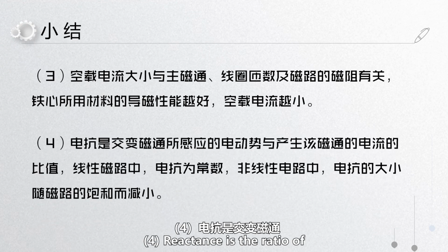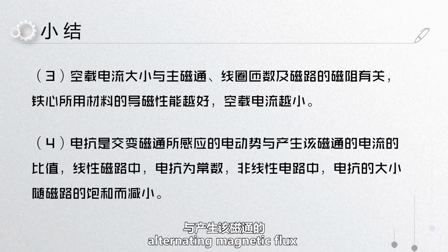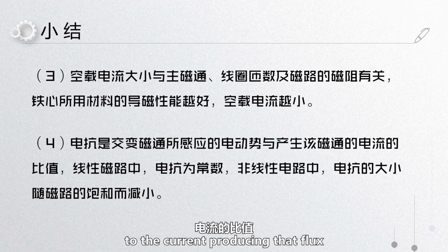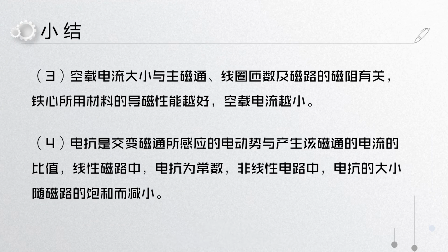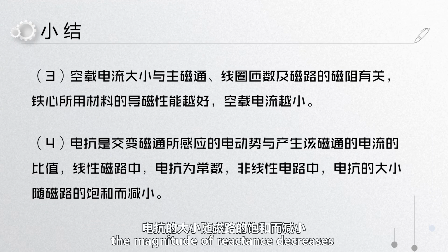Fourth, reactance is the ratio of the electromotive force induced by alternating magnetic flux to the current producing that flux. In a linear magnetic circuit, reactance is a constant, while in a nonlinear circuit, the magnitude of reactance decreases with the saturation of the magnetic circuit.